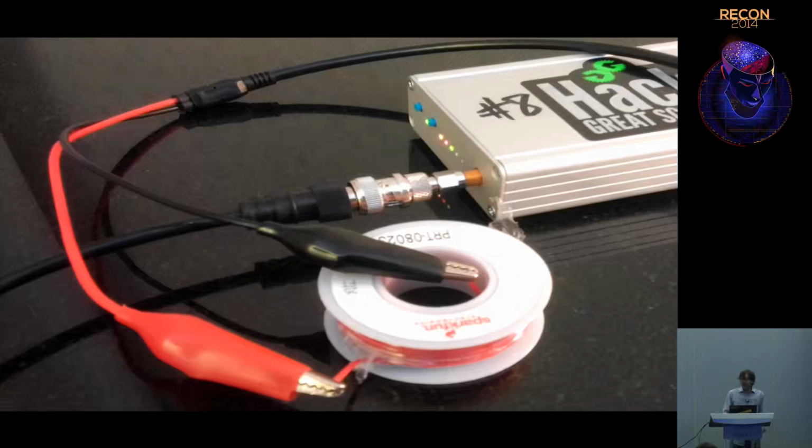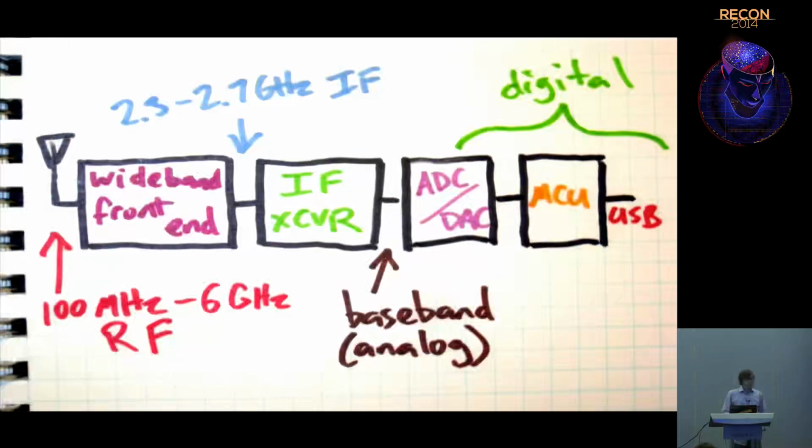The last thing I want to talk about is the high end of the operating frequency range. Now, I mentioned that the radio frequency that the HackRF is tuned to is the sum or difference of those two mixer frequencies. The one mixer can go up to about 2.7 gigahertz. In reality, it can go up to about 2.75 or 2.76. And then the wideband front-end mixer, I think it's advertised to go up to something like 4.2 gigahertz, but if you read the data sheet and look at how it can be configured, it can actually go up to 5.4.